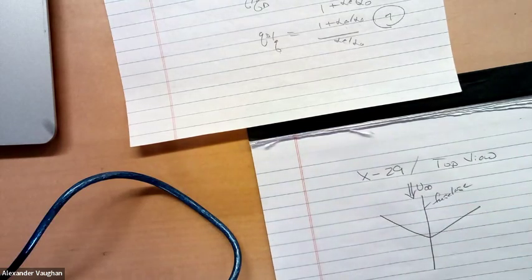It turns out if you sweep the wing forward, then divergence is usually more critical than flutter. If you sweep it back, flutter is usually more critical than divergence. And since most airplanes are built to be swept back, when they're swept forward, that's part of the answer to your question.